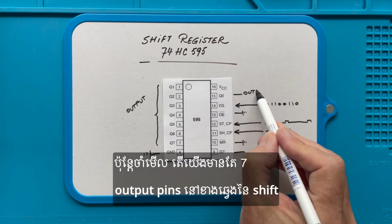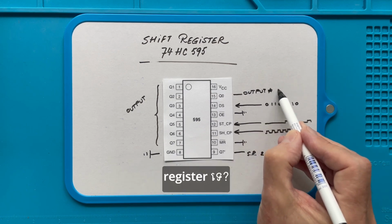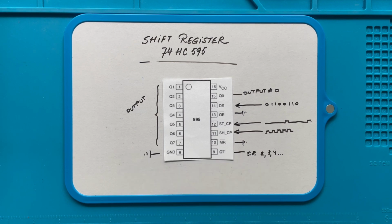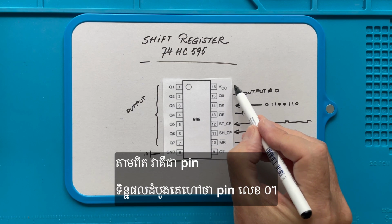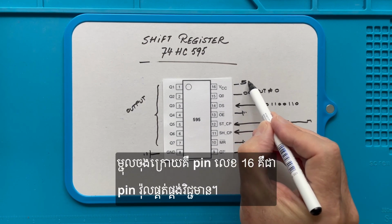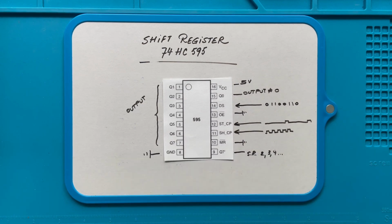But wait, don't we only have 7 output pins on the left side of the shift register? Indeed, but pin 15 is another output pin. Actually, it is the first output pin, referred to as pin number 0. The last pin, pin number 16, is the positive voltage supply pin.